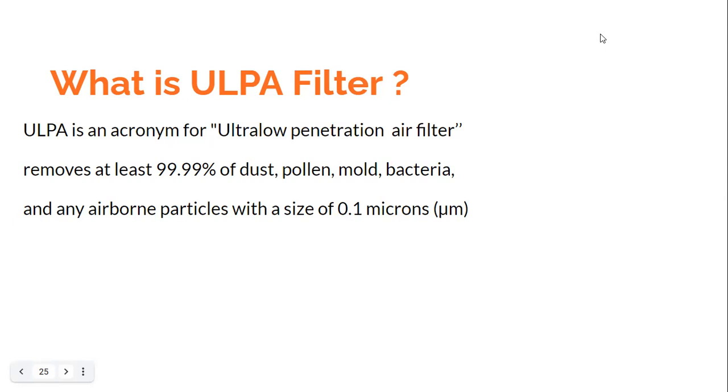And by all, we mean 99.9995%. Okay. So this is the ULPA filter. Remember that you would have different standards which would give you a slightly variant definition of what is a HEPA filter. For example, if it is EN 1822 standards, then this would define the HEPA filter in a slightly different way.